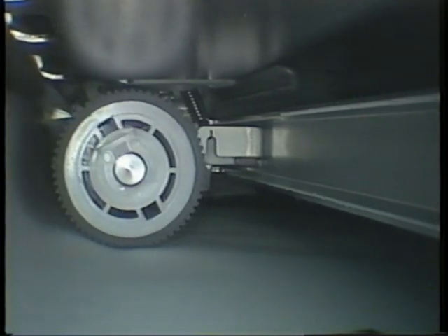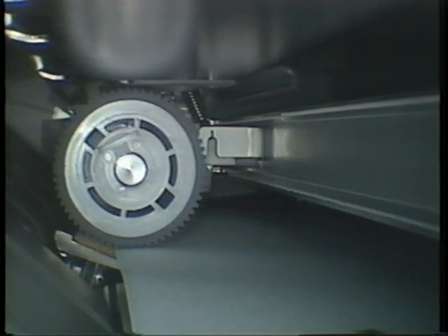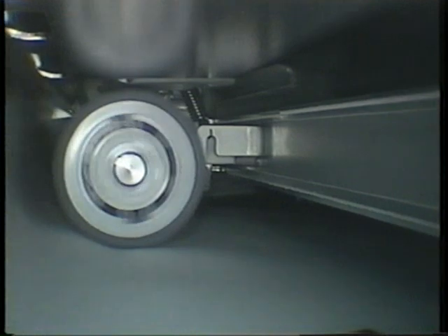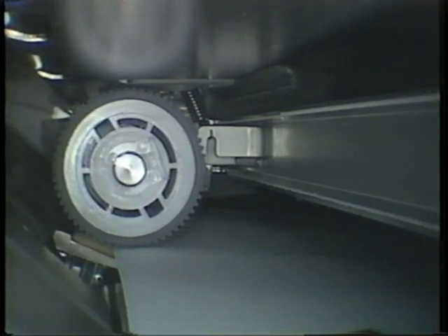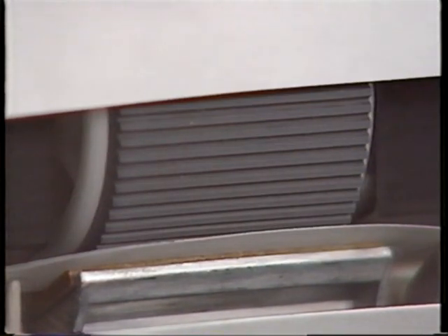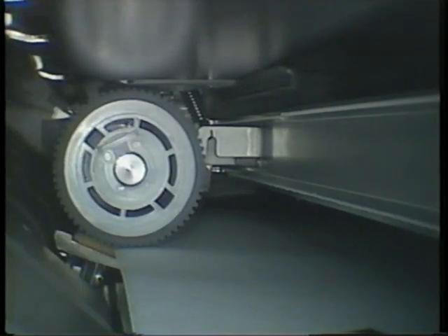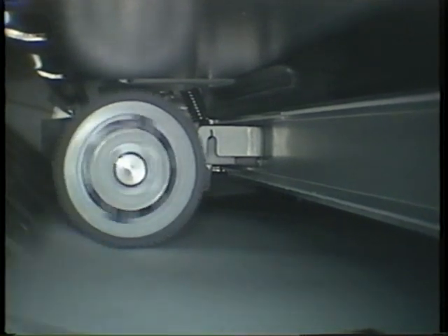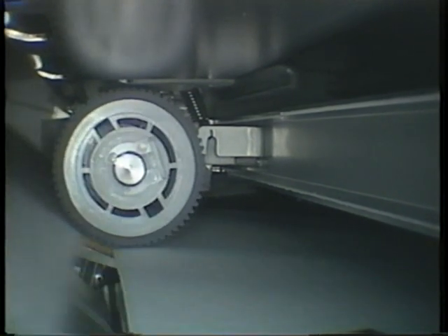When the feed roller starts pulling the top sheet into the machine, sometimes the sheet underneath sticks to it. This can happen simply from the friction between the two sheets. The friction between the bottom sheet of paper and the cork pad is greater than the friction between the two sheets of paper, so the pad holds the bottom sheet back. Only the top sheet feeds into the copier. The bottom one will feed on the next copy cycle.